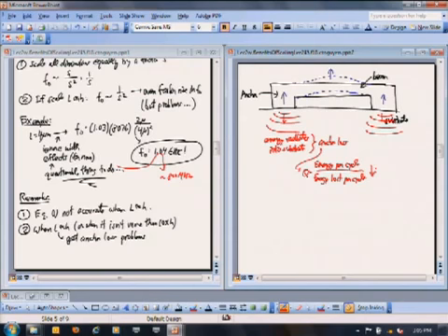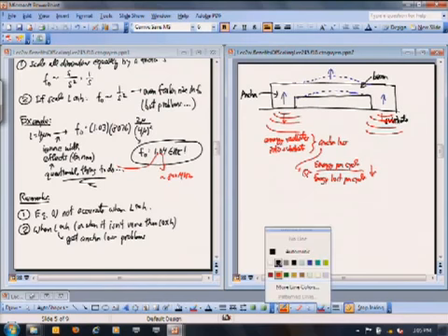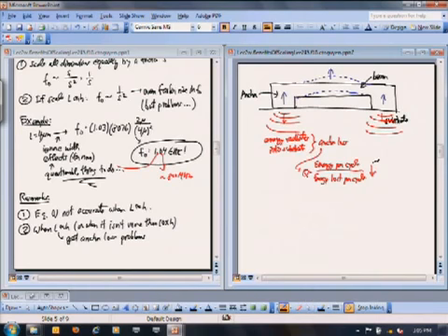Okay, so what are some of the solutions to this? So this is an example here, right, of one of the cons of scaling. Right? So scaling the length down to 4 microns raised our frequency to 1 gigahertz, but now we lose all our Q. There's a trade-off going on there. And so the engineer, right, the MEMS engineer has to think, how am I going to solve that trade-off? Okay, I want to keep that frequency, but I do not want to lose that quality factor.